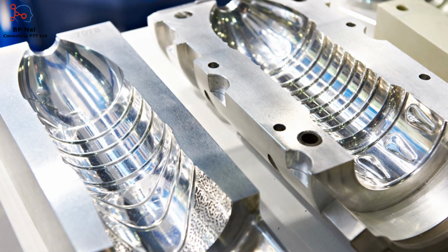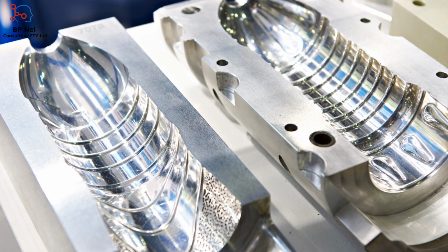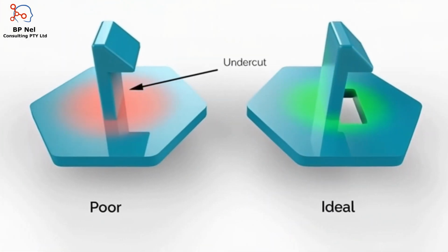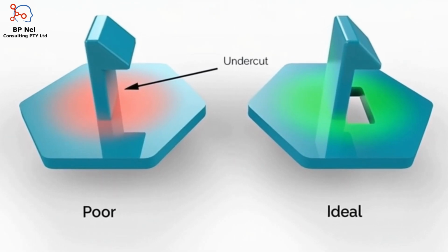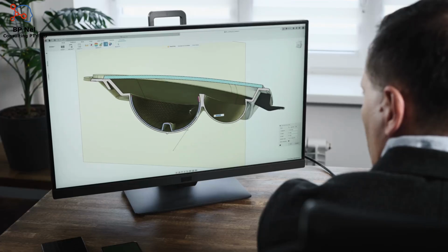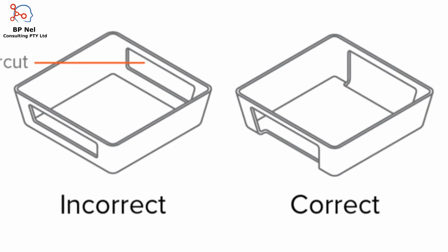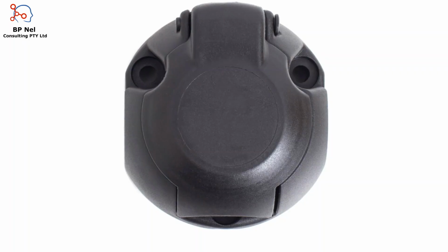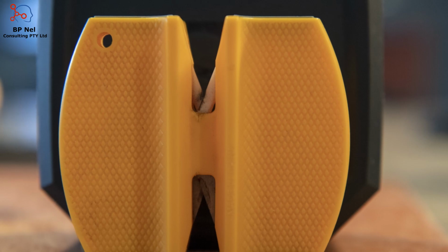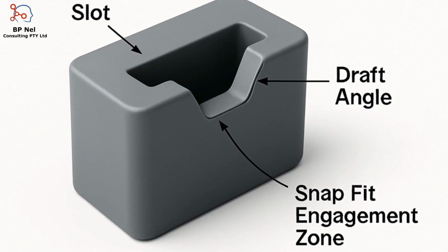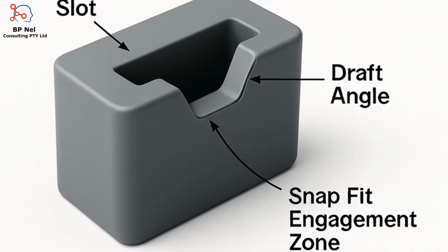The simplest molds are two-part tools that open in a straight line. Undercuts, features that trap the part in the mold, add cost and complexity. Avoid undercuts when possible by rethinking features. Use U-shaped cutouts or through holes instead of side holes. If undercuts are necessary, design them to minimize extra tooling, like adding slots next to snap fits.